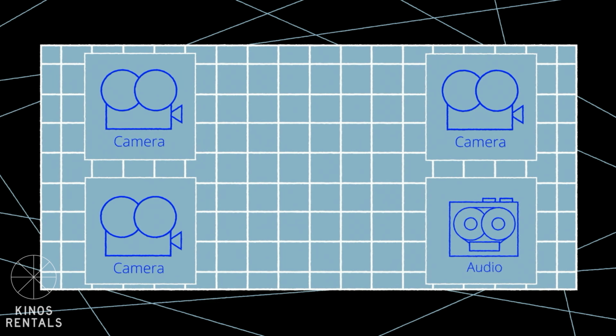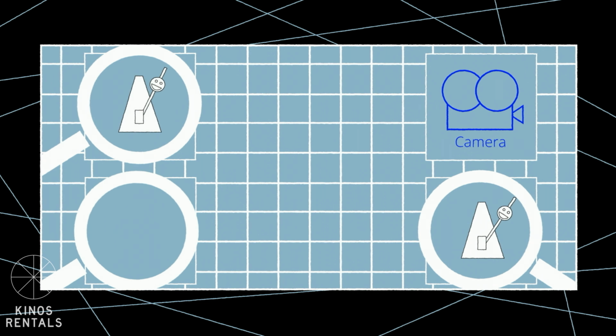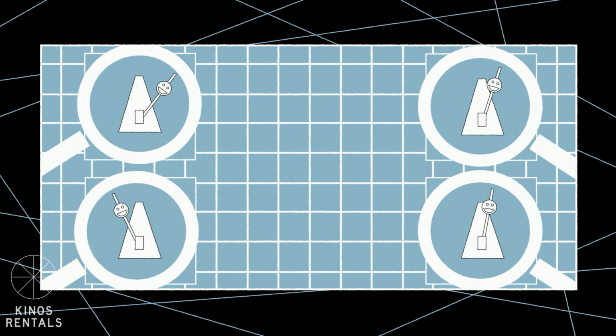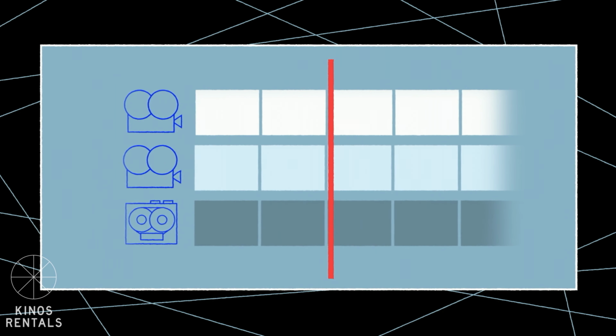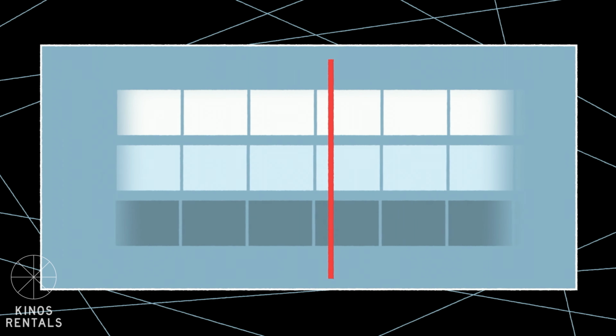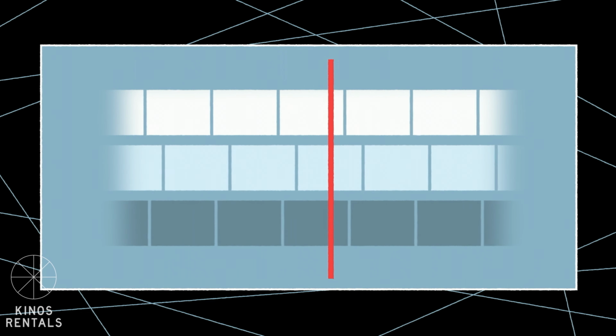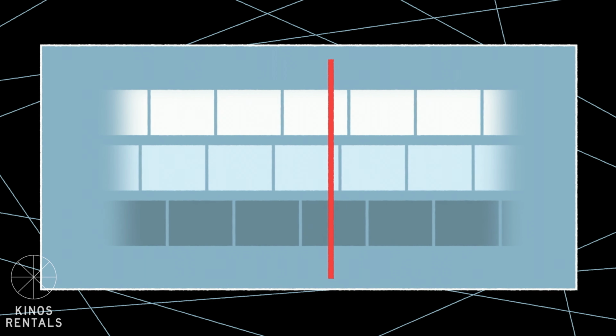Each device and its internal components operates at a unique speed determined by its internal processor clock. So within a camera, its internal processor clock determines the speed of the shutter, the video processing, and the A to D converter controlling its internal audio tracks. And each device's internal clock has a different level of accuracy, so even if you begin recording at precisely the same moment, the recordings captured at different clock speeds will gradually lose sync with each other beyond the first moment that they are played back in post.